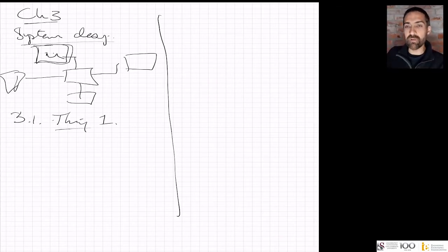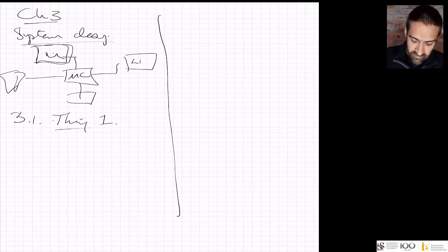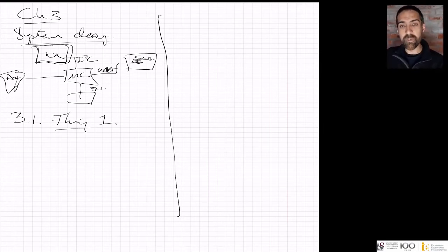So you fill your logical functional blocks with a bit more color to help the reader understand how you set this whole thing together. So when you draw this functional block, you want to say there's a microcontroller here. You want to say there's a sensor here. There's an actuator here. There's a power conversion here. There's whatever there is over there. And then importantly, what I also tell my students to do is just put in the interface between the functional blocks, like a UART or an I2C or a 5-volt signal, etc. So typically on the system diagram, you have the functional blocks. You give an indication of how the power flows work.